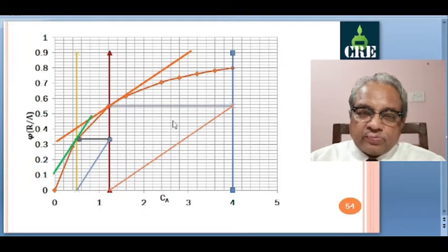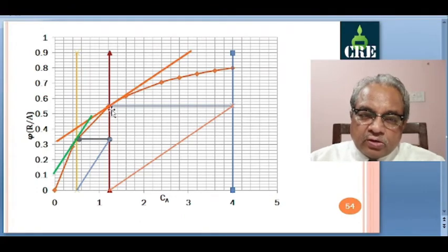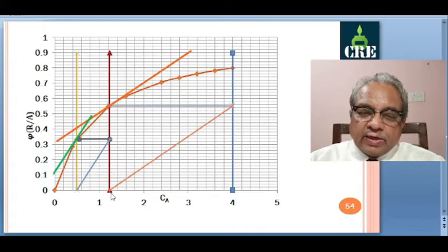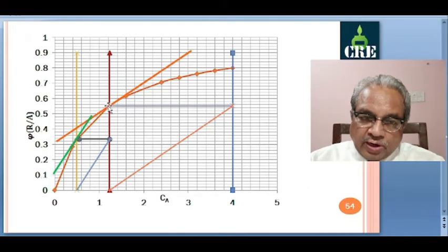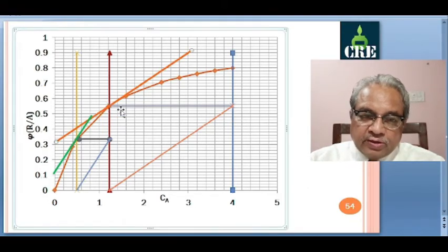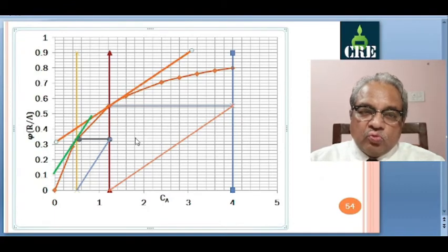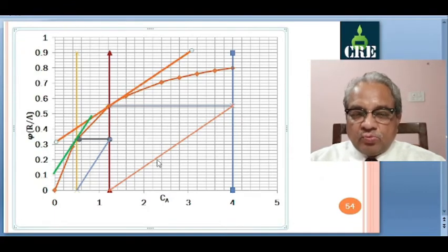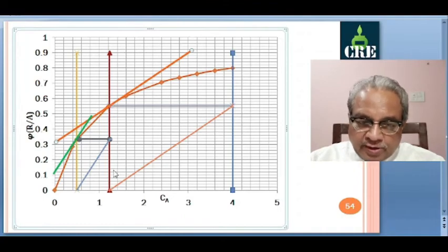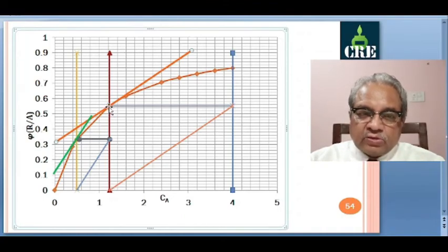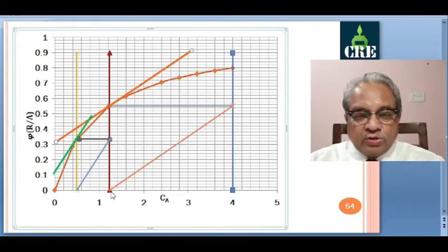Now here you can see we have to adjust this point on this curve such that from this, if you draw this rectangle, the slope of the diagonal of the rectangle should be equal to slope at this point from where you have completed this rectangle. These two slopes should match. Slope of the tangent at this point and slope of this diagonal should match. Then you find out this intermediate point. That is the best possible point. And that is 1.236 found out graphically.